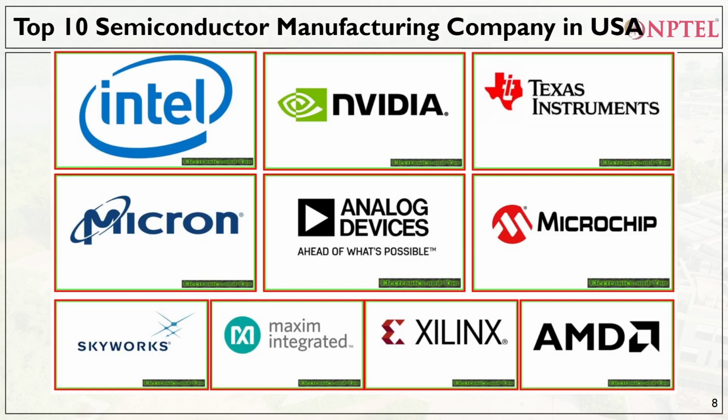And you have an FPGA where you can demonstrate the things. The other flow is an ASIC flow, where you design an RTL design, but what you do, you go through the ASIC flow, you do the synthesis using some of the Cadence or Synopsys tools, then you do the placement and routing, we design a chip, then you send the chip to the foundry, right? And then you get the final chip. So irrespective of the flow and all, the basic first step there is the design using Verilog.